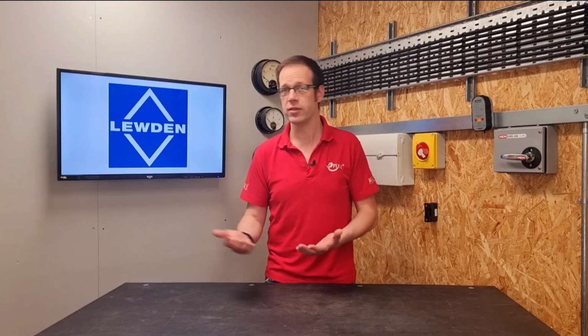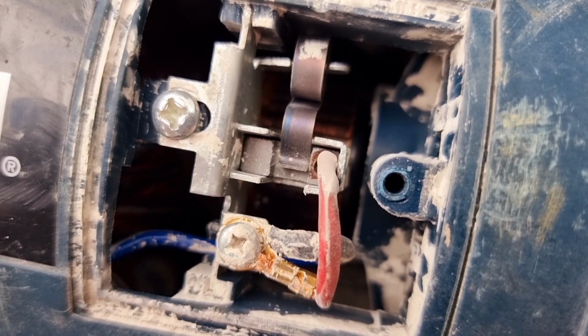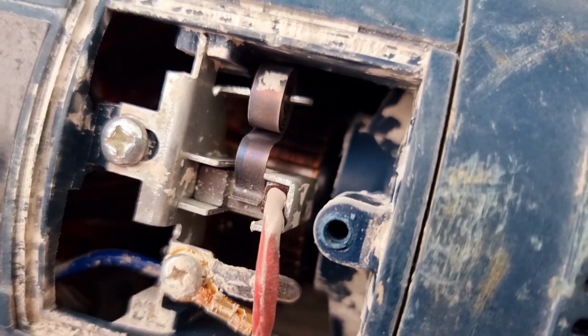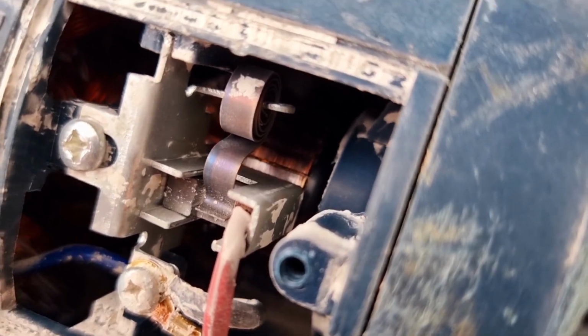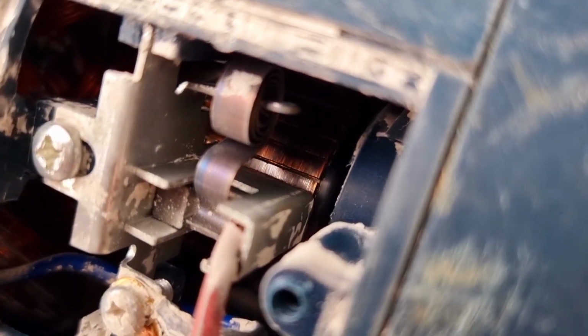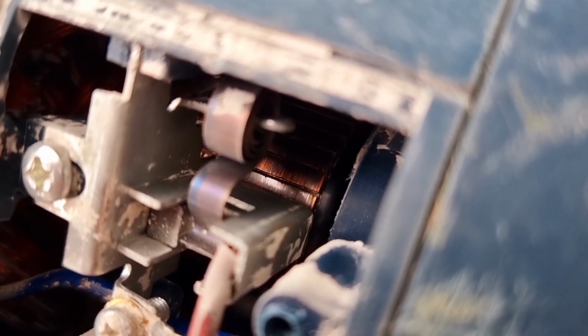However, as electricians, we know that electricity can create sparks, even in healthy equipment operating totally normally. For example, common household items that use motors such as drills or hairdryers will often produce sparks during normal operation. It's simply caused by the connection between the carbon brushes and the contacts on the motor. When the motor spins, it can bounce the carbon brushes back a bit on their springs so that there's some moments of disconnection and reconnection.